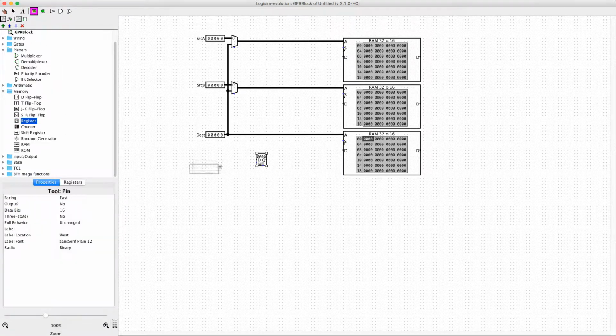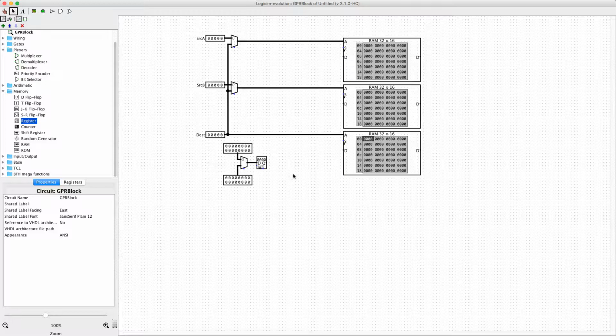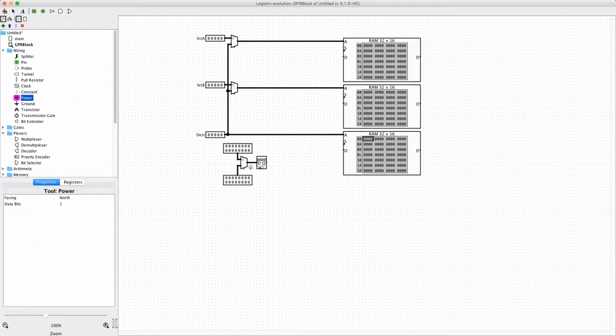I should just use an array of registers, since that's what the GPR block is, and multiplex the registers together. That way, I don't have to worry about keeping 3 copies of these registers synchronized 100% of the time, because there will only be 1 copy, which will by default be synchronized with itself.